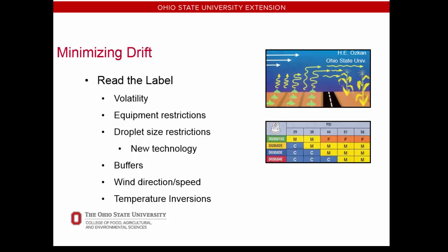Orchard sprayers require that nozzles be directed at the target and that only one side of the sprayer can operate on the outer 2 tree rows. Other labels require specific volumes of spray be applied, so calibration is critical. Many newer labels state a specific droplet size classification that must be used, and some recommend use of new low drift technologies. Today there are labels that specify a buffer or no spray zone adjacent to an application.